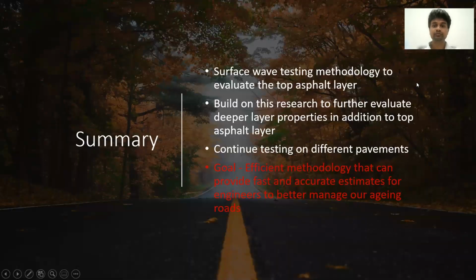So in summary, what we have is a surface wave testing methodology to evaluate the properties of the top asphalt layer. Going forward, we will build on this research to further evaluate the deeper layer properties in addition to the top layer properties, and we will continue testing on multiple different pavements with the ultimate goal of developing an efficient methodology that can provide fast and accurate estimates of pavement properties for engineers to better manage our aging roads.